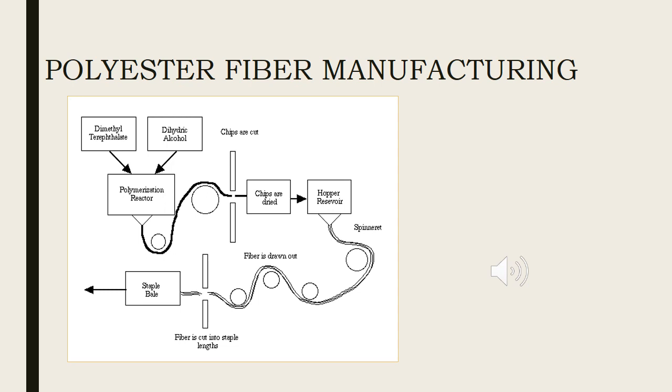The filaments from each spinneret are collected together to form a small ribbon, passed over a wheel which rotates in a bath, and this ribbon is then mixed with ribbons coming from other spinning positions. This combined ribbon is called tow and is coiled in canes. This material is undrawn tow and has no textile properties. Then comes drying, annealing and cutting.